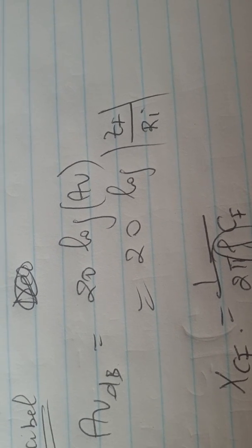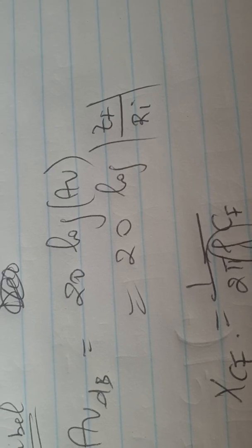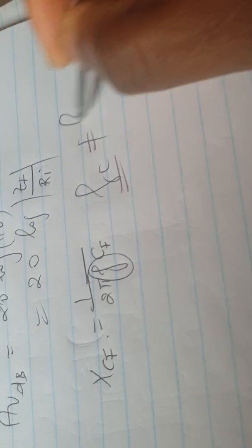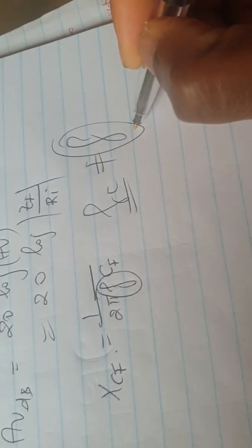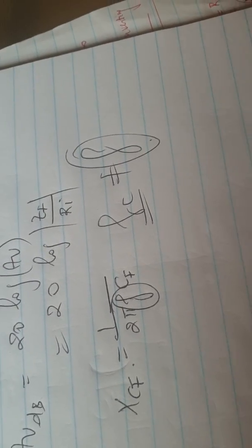To answer that question, we will normally be given the operational frequency. That frequency, first of all, is different from cutoff. This frequency at which we are calculating XCF is the frequency of operation of the operational amplifier, and that will normally be given to you. So for instance, if you look at example 5317, it clearly said that the amplifier is operating at 0 Hertz in one case and at 1 megahertz in the other case. And that frequency is nothing but the frequency of the input signal.